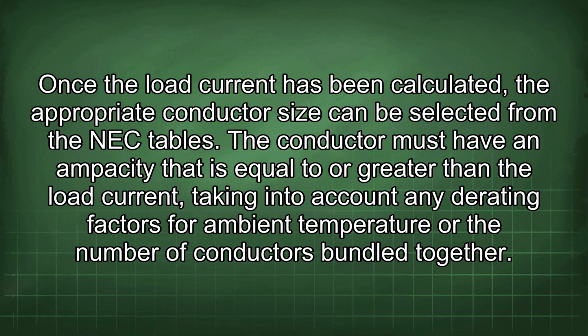The conductor must have an ampacity that is equal to or greater than the load current, taking into account any derating factors for ambient temperature or the number of conductors bundled together.